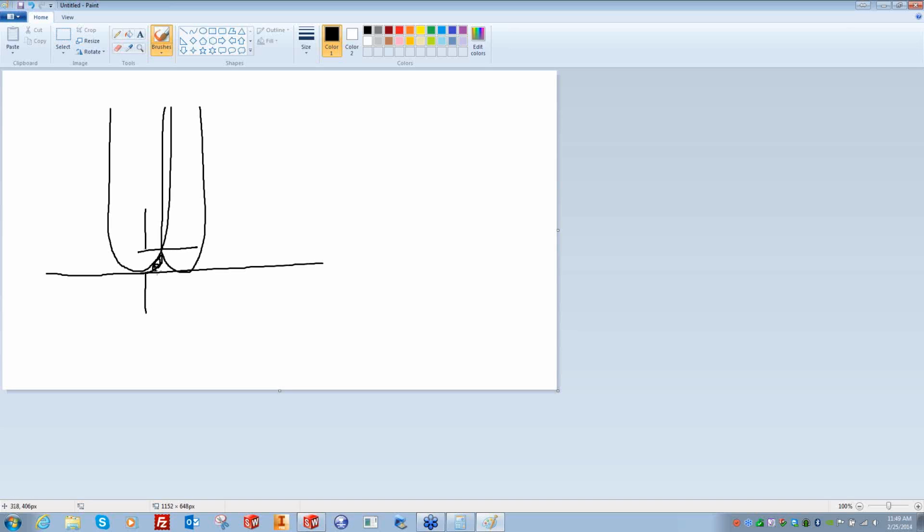So we're talking about this area in here, all this black. So that's a scallop height. And it is in direct relationship with the step over from the tip of the tool. Okay? So you got a distance here, you got a height here. So this is your step over value, this is your scallop height right in here.